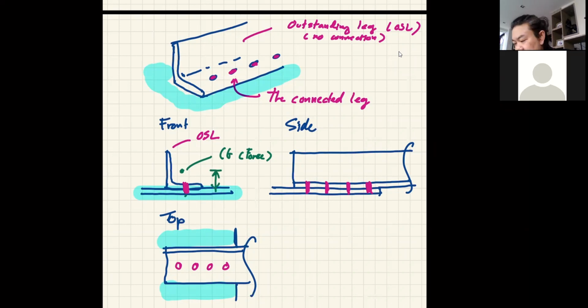In other words, it's the X bar of your cross section. And this becomes the length of the connection that gives the opportunity for the force to go through. The shear lag factor can be calculated by simply using this formula: 1 minus X bar over L. Is there any question? Oh, I kind of like this picture. Any question?